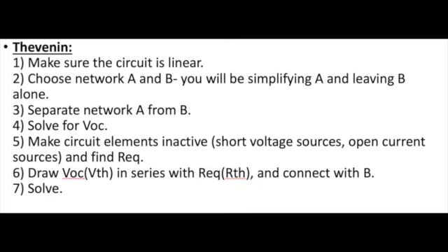Then calculate REQ. REQ, otherwise known as the equivalent resistance, is calculated using series and parallel resistor rules to find one singular value for the entire resistance of the circuit. Finally, draw VOC in series with REQ and connect it back to the load B.